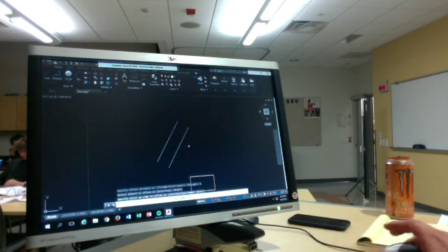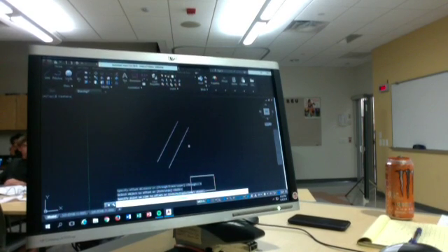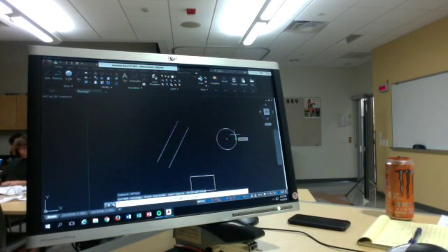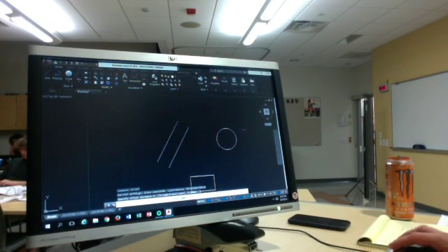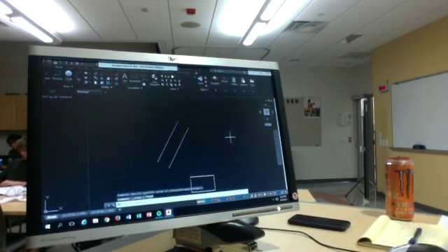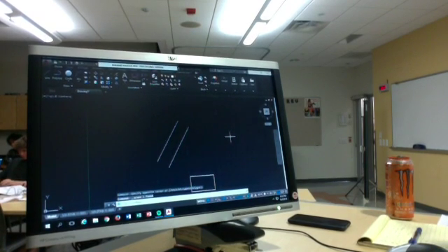So you click, it offsets it for you. You can also make that work on circle. So offset. Say we're going to offset at 1. Works on circles too. It'll work on pretty much any form of vector object that you can possibly come up with. So drawing a circle, I know I went over a little bit of that earlier.